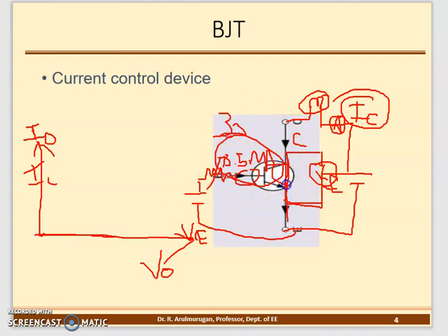If I vary this RPS, say RPS 2, whenever I increase it, the potential difference takes place, but current does not flow. So the output voltage is increased, but the output current is 0. My input current is 3 milliamperes, my output current is 0. So 3 milliamperes is insufficient to turn on.